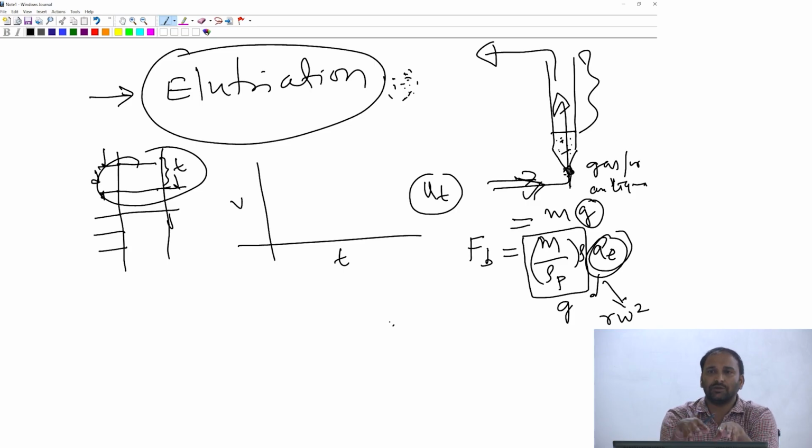So you should also think a little bit about working out the equation that we developed for cases of other particles. We looked at a simple case of a spherical particle, but you can also develop similar expressions if you're thinking about settling of, say, a cylinder. If I have a cylinder falling with this configuration under the influence of gravity, then your AP, which is the projected area, is going to be the area of a rectangle, right? Your length times the diameter. So you have to take the appropriate AP.